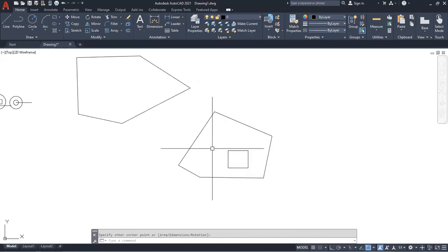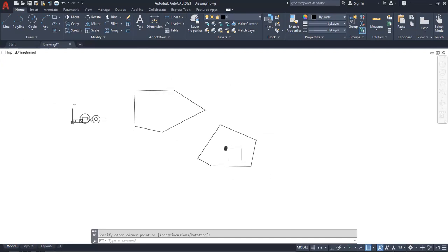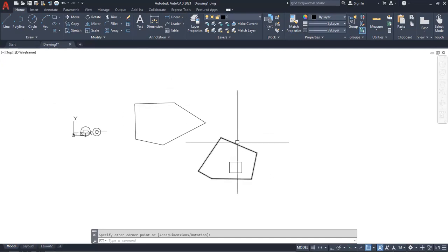So that geometric center is based on all the average dimensions of the geometry, and it will give me an exact geometric center. So for geometric center, it's important that I have a closed geometry. Since here I had a segmented geometry, it couldn't calculate the center because it was treating it as individual geometry and not a closed geometry.